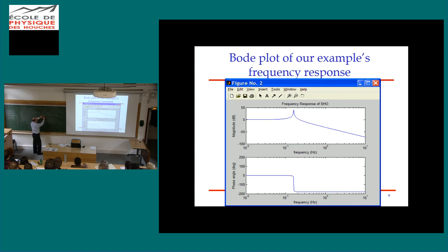At a special frequency, the real part of the denominator vanishes. That frequency is root k over m for a mass on a spring. That's the resonant frequency that we learn in first year physics. If I had no damping, my model would predict the unphysical thing, that the response would diverge. Sometimes the damping is very low, and for all practical purposes it's diverging and you're in danger of breaking something. Please don't. But this damping is always there at some level, and it's what prevents things from diverging.